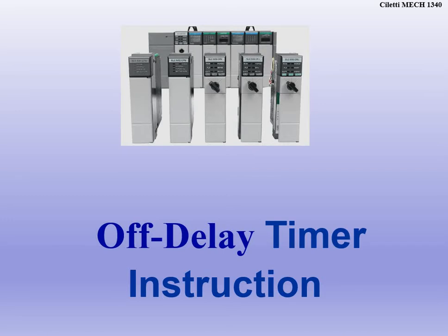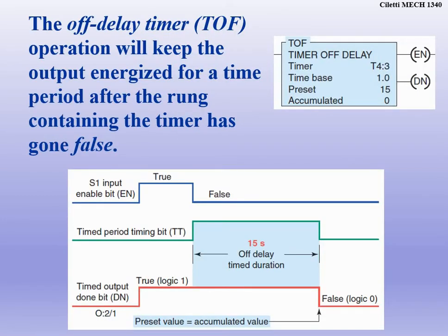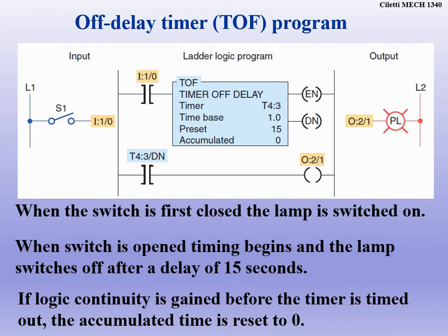Same kind of concept goes. We're off delay timer instructions here. Just the setup is the exact same as the on delay, only we're using an off delay. So I'm not going to spend a lot of time. You guys will have access to the slides, or you can pause the video and take a look at and see what goes on and how we control some things. But remember, an off delay timer means that it's not going to start until we de-energize the switch.